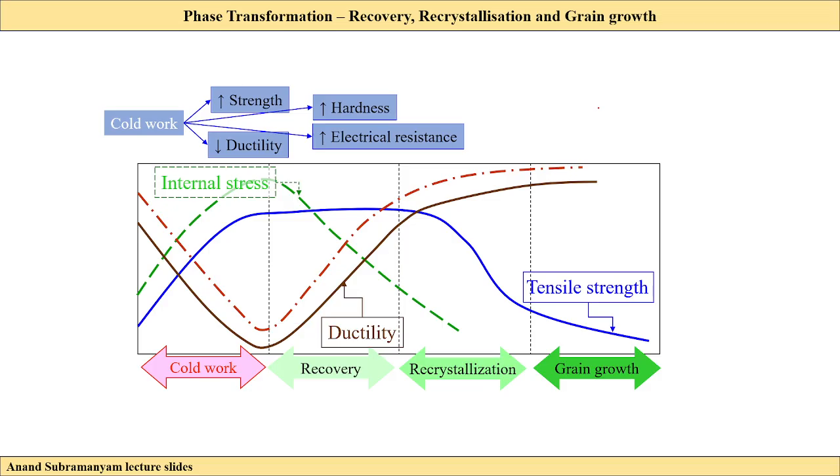When I'm discussing strength, there are two points that should come to mind: one is the yield strength, and the second is the ultimate tensile strength. When I'm talking about strength, I'm directing towards these two points. Yield strength is the minimum amount of stress that needs to be applied for a material to start plastic deformation. In more layman terms, that is our yield strength.